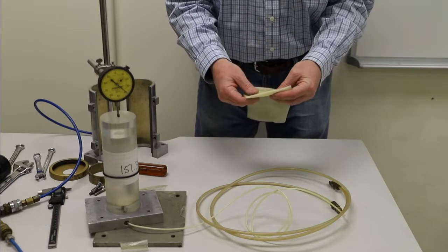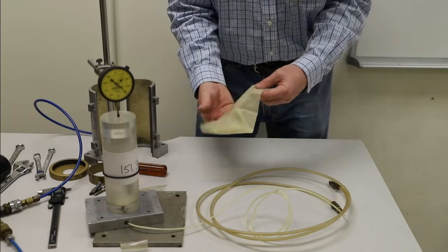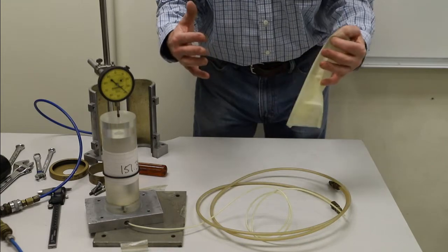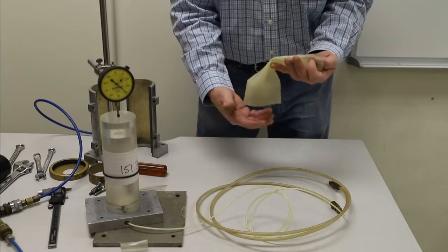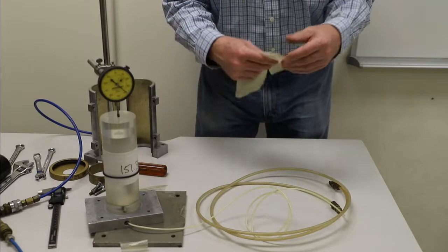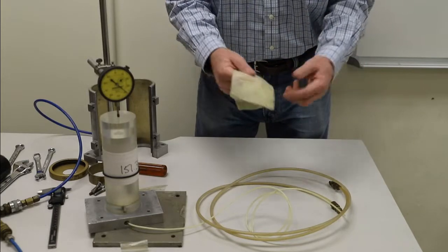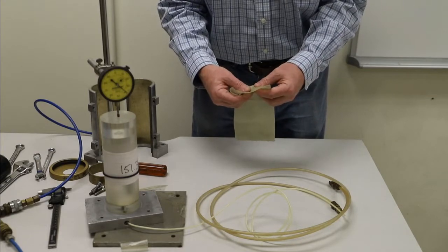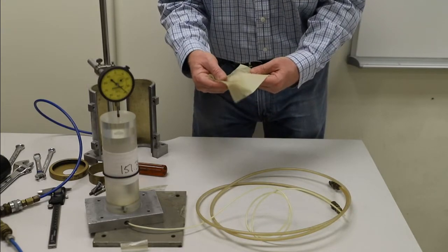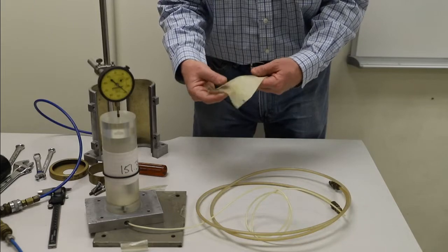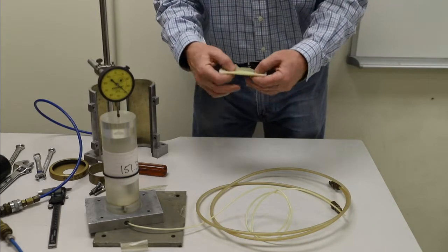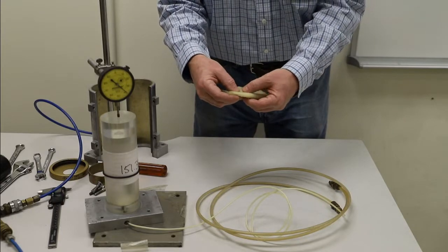The other one, we're going to have a membrane. This latex membrane is going to seal around the sand grains, make sure that the pressure outside the membrane can be maintained different from the pressure inside. That's how we're going to have effective stress on the sand. And so we need to know actually what the thickness of this membrane is. So we're going to fold it into 8 layers.